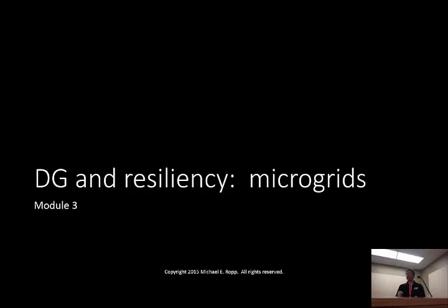It's more sensitive to a VAR mismatch than a watt mismatch. Generally speaking, if you've got an active anti-islanding method in there, you've got to be matched to much, much closer than 1% in order to get enough of a match that the active anti-islanding wouldn't see it. And that's why we've said before that this is a very low likelihood event.